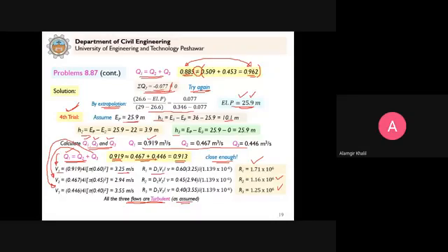So now we have found out that all the three flows are turbulent. Here you can see the Reynolds number for turbulent flows as we assumed. So now we get the correct values of Q1, Q2 and Q3. This is what was required to calculate the discharge Q1, Q2 and Q3. So these are the correct values for the discharges. So this is how we proceed to solve case 3.